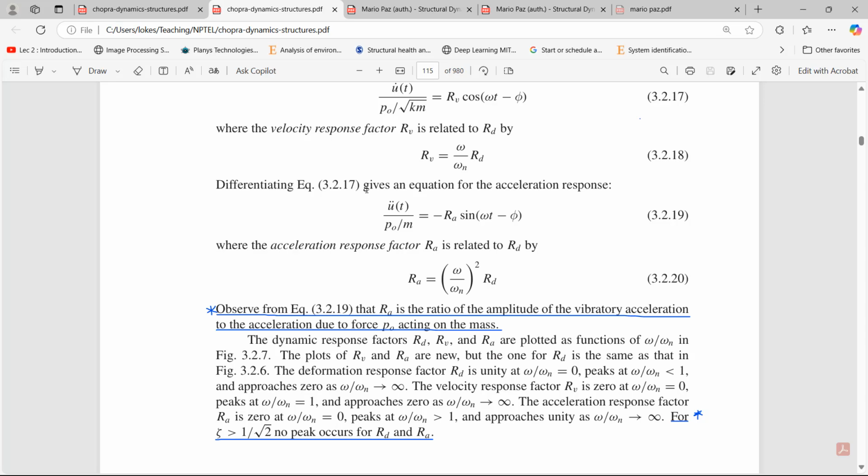So we have this thing, and then there will be other sensing elements which convert the displacements experienced by this SDOF system into electrical signals, which we get as output. These are capable of recording only the relative displacement between the support and the mass. That means we are able to record only the u term, but not the total displacement which is being transmitted to this mass.